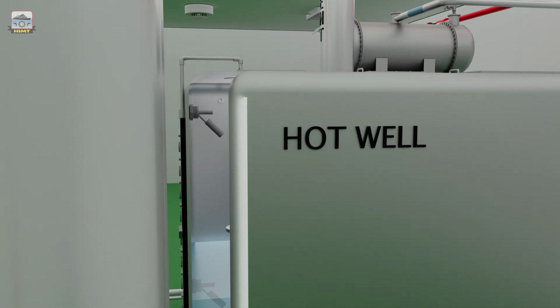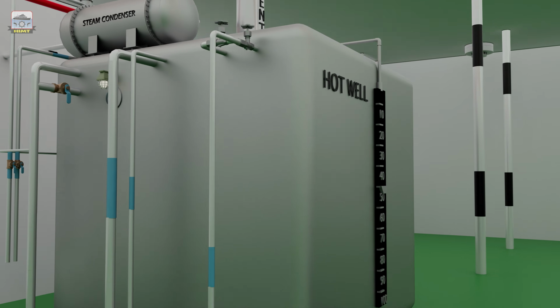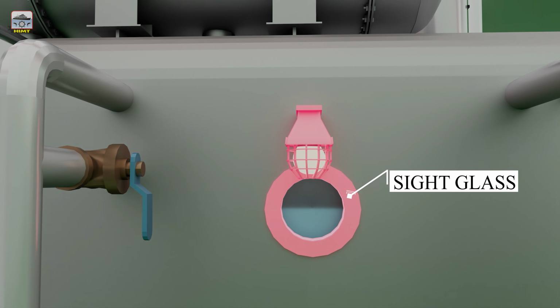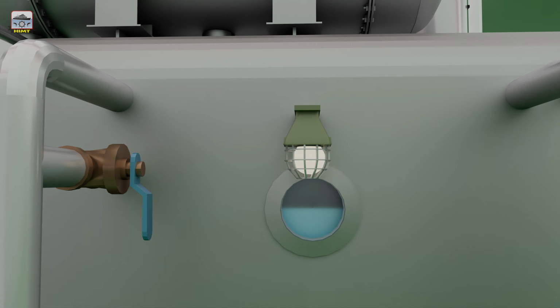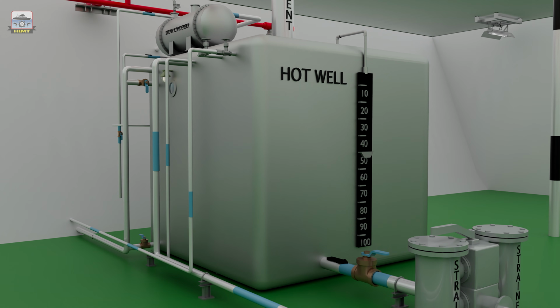The hot well is also called an observation tank, as it is the place where the operator can observe whether any oil is coming along with the condensate return line from the heater due to a holed or cracked heating coil. To facilitate this observation, a sight glass with light is provided on the side wall of the hot well in the first chamber. The entire quantity of water fed to the boiler does not return to the hot well from the condenser due to the following reasons: the leakages in the systems.